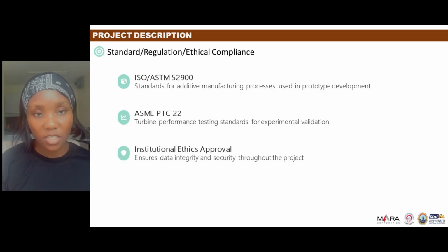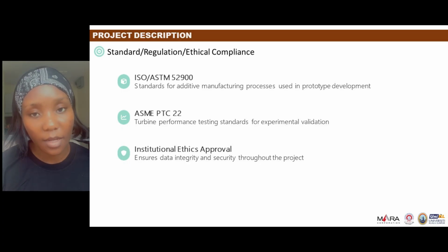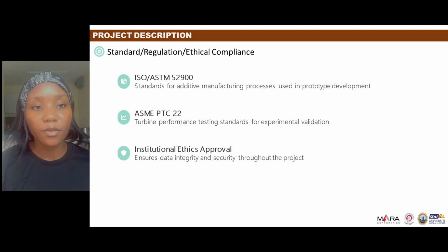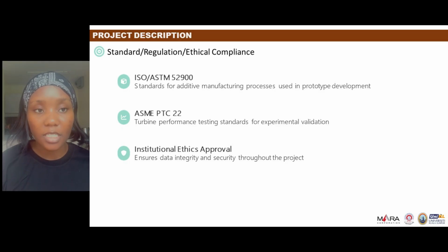hotspots or temperature variations. In addition, precise pressure sensors will be strategically placed around the blade tip cavity to measure aerodynamic flow characteristics. These measurements help to identify areas of tip leakage flow, vortex formation, and associated aerodynamic losses. Together, these experimental measurements allow us to compare actual physical behavior with the computational fluid dynamics predictions, providing critical validation of simulation models. By integrating experimental data with simulations, we can refine and improve the models by increasing their accuracy and confidence for future design iterations.